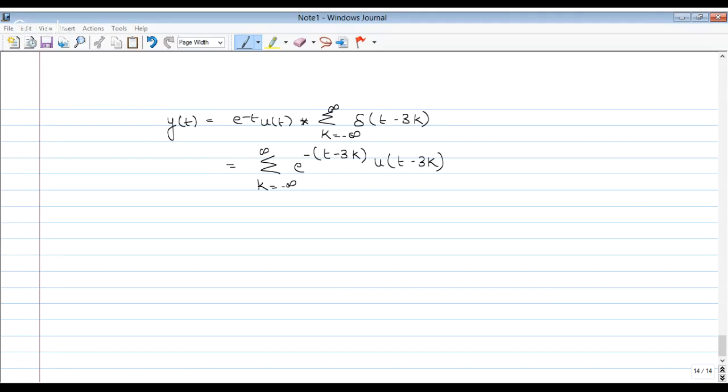So Abhinjan is saying I have a doubt on reactive power flow and capacitive current flow in leading power factor case and lagging power factor case. Capacitor will always operate at a leading power factor. See, you assume it to be IC. If the direction of IC would be different, then definitely your IC would be negative if the capacitor delivers current. So you do not have to worry about the direction of current. You always assume that current enters the positive terminal.